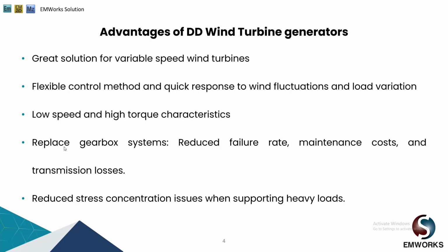This is important for offshore wind power design, where the weight must be supported on a floating surface. The third advantage is that with fewer moving parts, direct drive design is less complicated to maintain and its maintenance costs are reduced over the long term. Again, this is especially important in offshore wind farming because of the difficulty in maintaining a generator at sea.